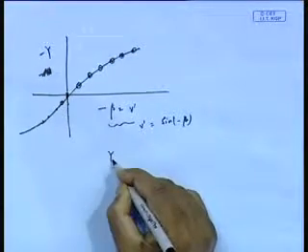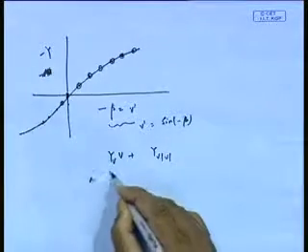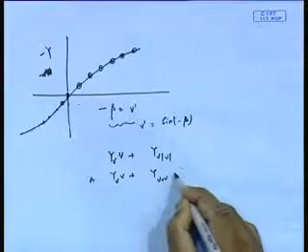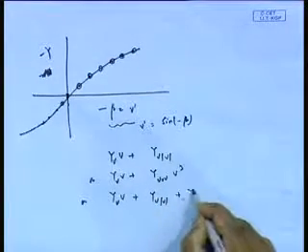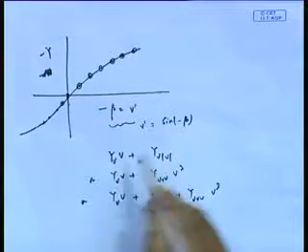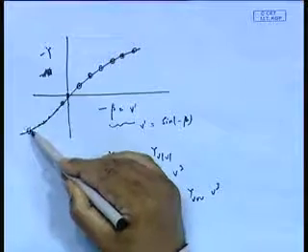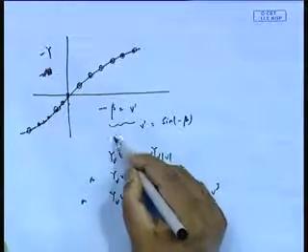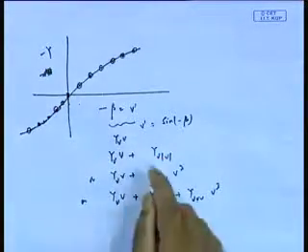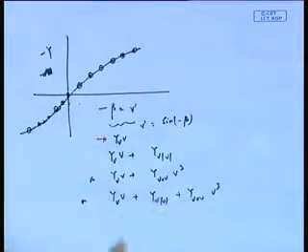Obviously, I can find out Yv. See, now what is happening, Yv v plus, depending on what model you do, this or Yv v plus Yvvv cube, or I can even do a combined model. Now the question is like that, I have this value, or let me put also linear value only. So, this is pure linear. Suppose my model was pure linear, I want to use this in conjunction with linear equation of motion.